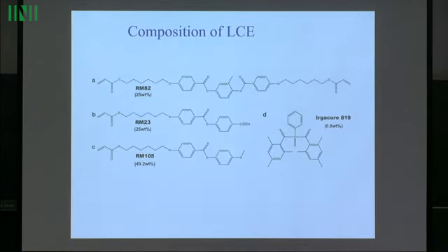And this is the chemistry of the work. So you see here so-called monomers. They have relatively rigid central core, similar to normal liquid crystal molecules. But then at the ends, you see these open double bond groups that are very likely to polymerize with each other if you have some ingredients such as promoter of polymerization and act, for example, with ultraviolet light. So when you have this mixture, you can polymerize it, and you would obtain a liquid crystal with rubber-like properties.